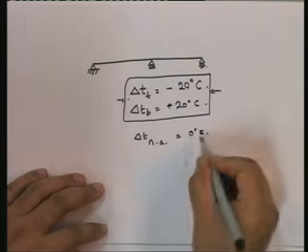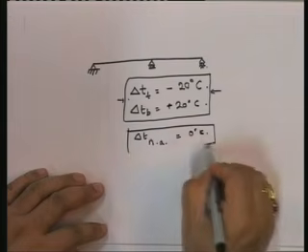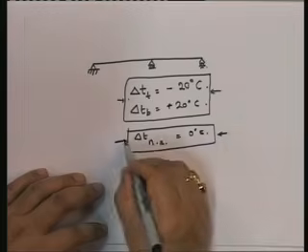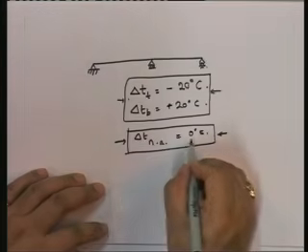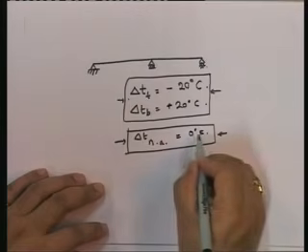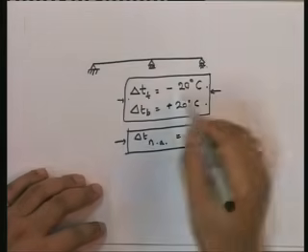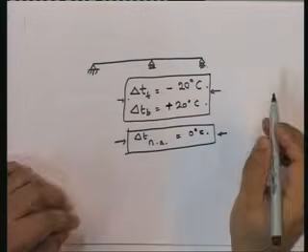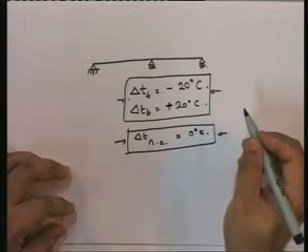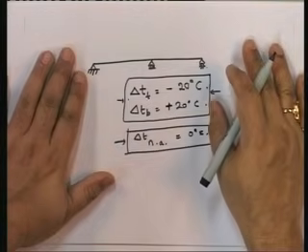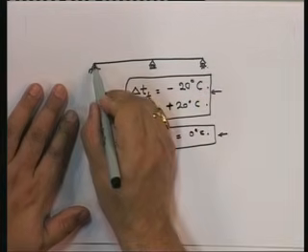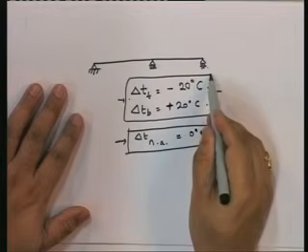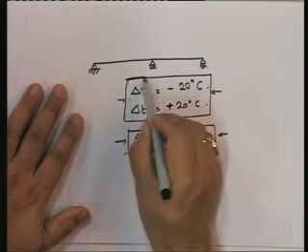In other words, this temperature differential leads to pure flexure, because at the neutral axis point there is no strain. That's why I am setting up a pure flexure kind of a situation. And there is no other load. And I have to find out the bending moment in this indeterminate structure due to this temperature differential.